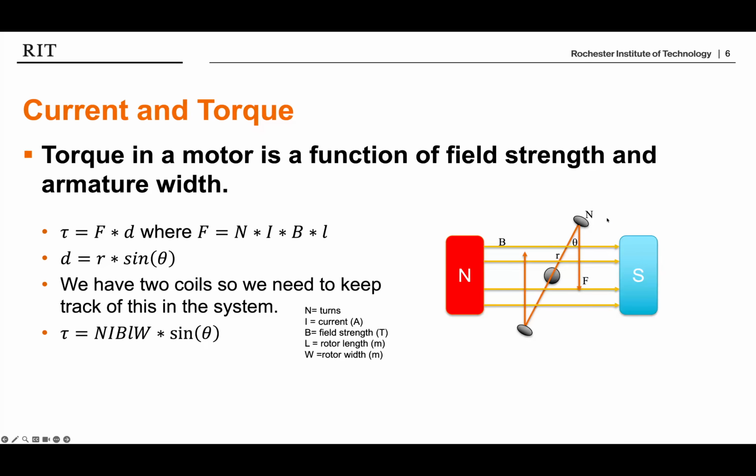So let's focus for a second right up here on this coil, the side of the coil that appears as though it has a north pole. And remember, we're using this north and south here for the EM field as a designator, right? So this appears as though it would be a north-poled magnet. That does not mean that there is a north pole magnet there. Okay, so again, I have something rigidly linked at a distance, and this thing is at some angle to this permanent magnetic field. Now in physics we use beta or B as our magnetic field strength, often in something like Teslas.